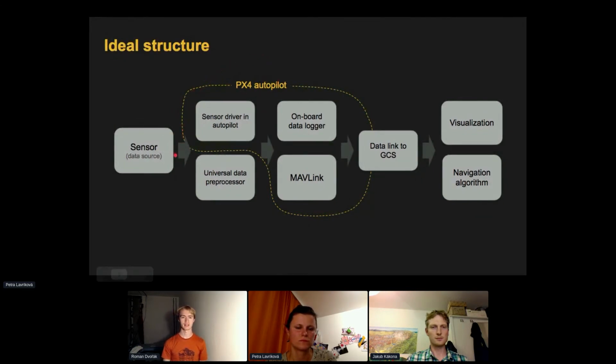This can be implemented by some device that reads the sensor and composes MAVLink messages itself and sends them to the autopilot. Or it can be programmed directly in the PX4 firmware. It is very useful to log this data on board because this log is not affected by subsequent systems such as telemetry. It requires high quality and highly reliable data links.